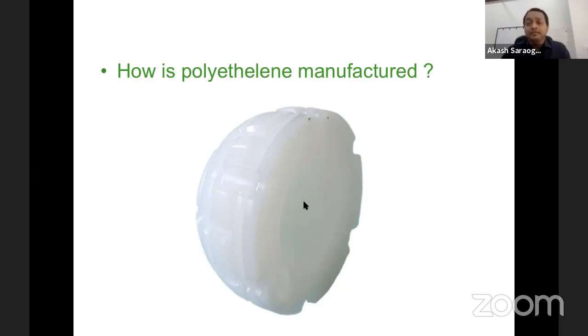Why is it better? Because the surface finish, the oxidation at the surface, which you can prevent, all of these is better with direct compression molding. So someone asks you in the exam, what way ideally should a plastic be manufactured? The answer is direct compression molding, right?